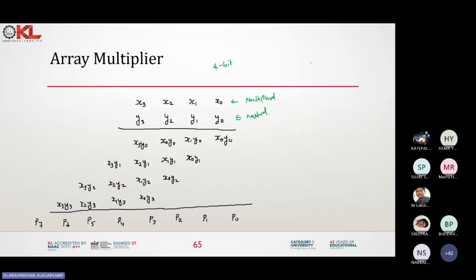It may be applicable when the multiplication rate is very high, but it is unnecessary here to bring in a shift register, because you increase the complexity of the circuit. An adder is a very simple circuit for multiplication operations, so we use combinational circuits here rather than sequential circuits. Am I clear? Okay, sir. Good. Any other doubts?